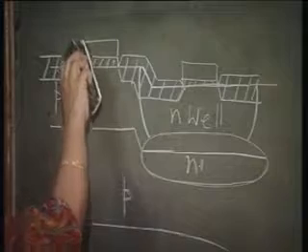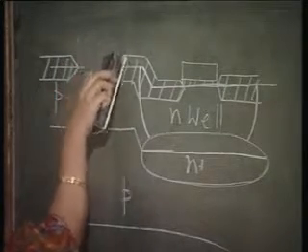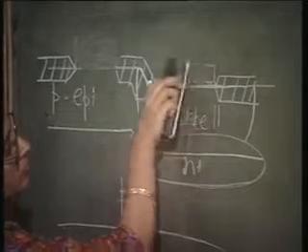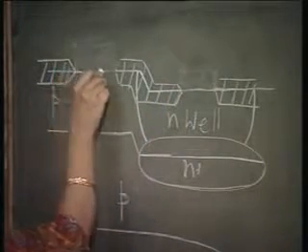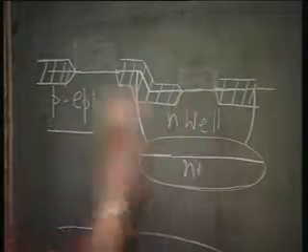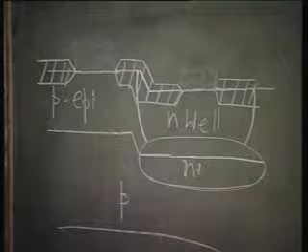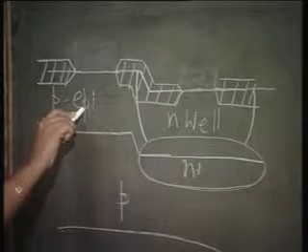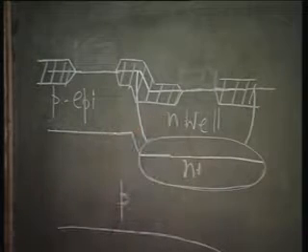Remove the oxide nitride mask. So, this is the region where you have your NMOS, this is the region where you have your PMOS.